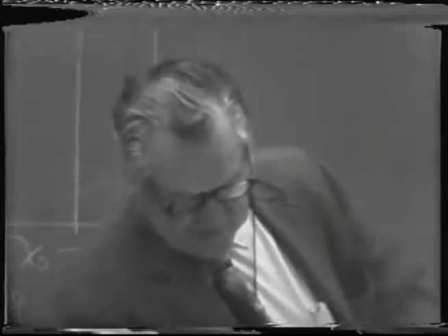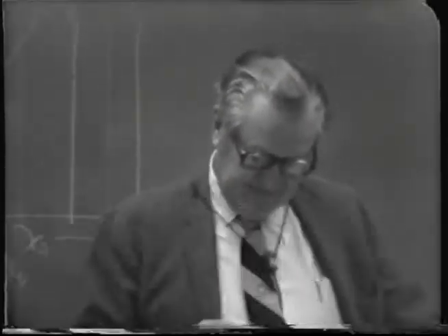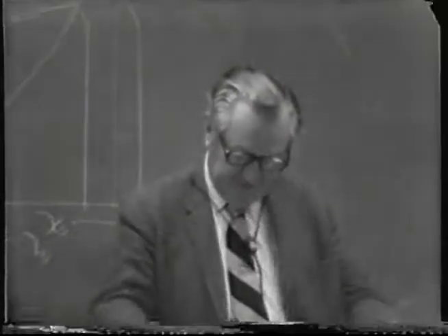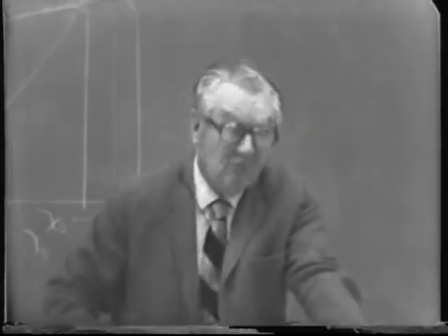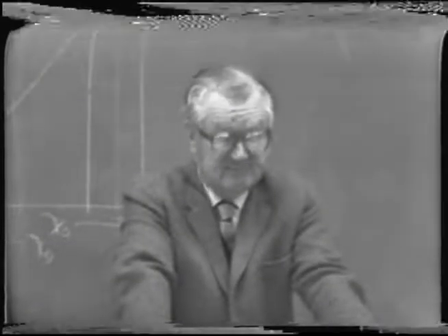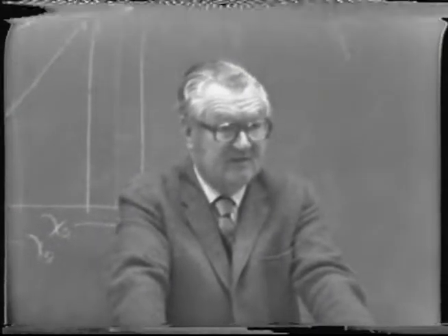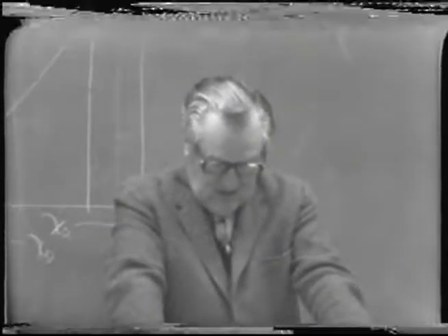So if you accept these figures, they aren't necessarily exactly what you'd get if you use some other parameters for calculating it, but anyway, I've recommended, partly on the basis of these calculations, that plate spacings in the rectifying section ought to be of the order of 12 inches minimum. And most of them from now on are built that way in the alcohol industries.